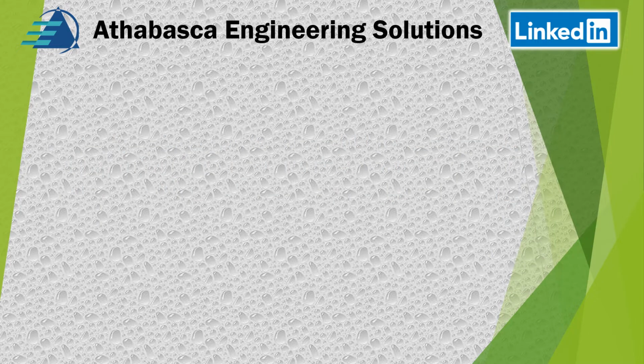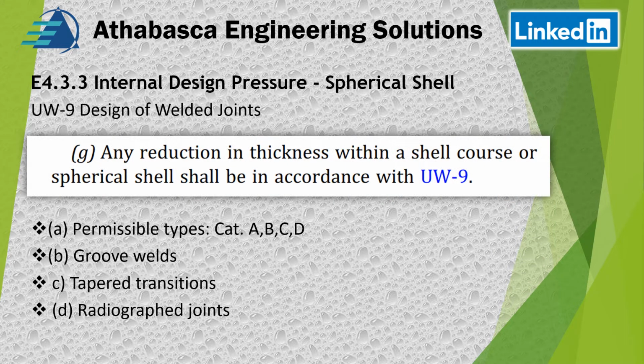We're going to continue on to design of welded joints, UW-9, and any reduction in thickness within the course shell or spherical shell shall be in accordance with UW-9. Basically, if you go through that, some of the key points are you have to use the A, B, C, or D permissible types of joints.